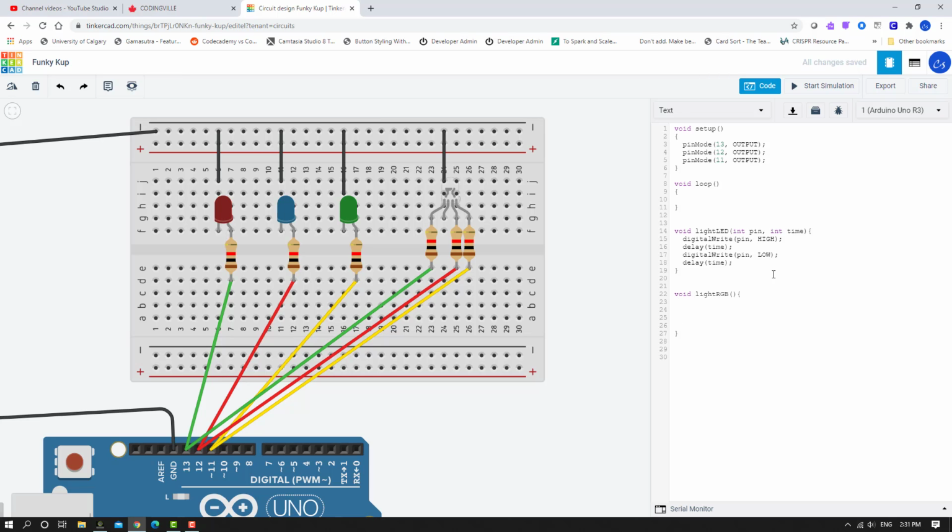First thing we need to do is figure out how do we turn multiple pins on at once, and how many pins do we have accessible to us. Well, in this RGB LED, it's pretty simple. RGB, red, green, blue, we have 3 pins, okay, 1, 2, and 3. So we just need to be able to modify those 3 pins at once. And because these are hardwired in, I think we should hardwire in our pin for the learning point of this video. So we'll go digitalWrite, and we're going to call pin 13, and we're going to call it HIGH, and we're going to copy that.